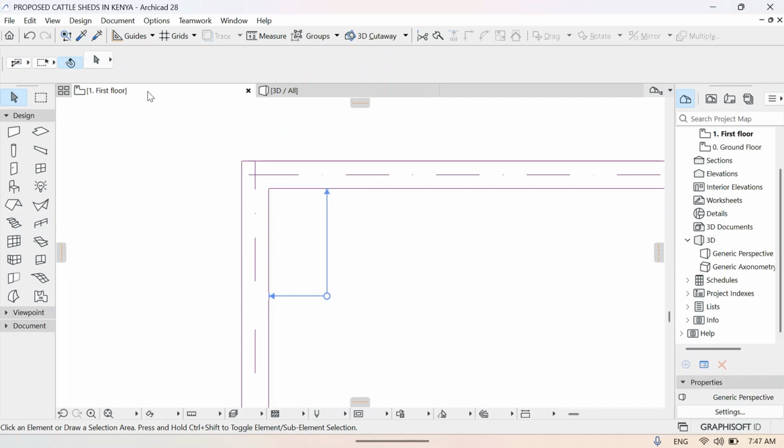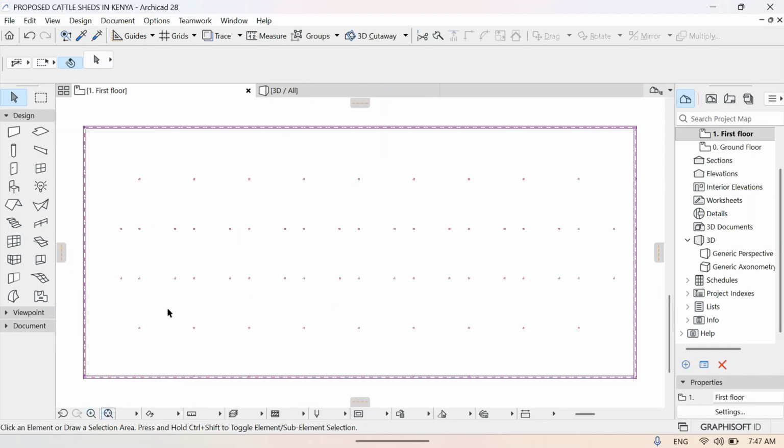So that's good enough. Our next step should be, I want us to have steel beams that will span from this edge, from here all the way to there. It will double as a binder for the openings, for the door openings here and here, will be part of the framing, and also act as a wall plate for our roofing. So we can get right into it.